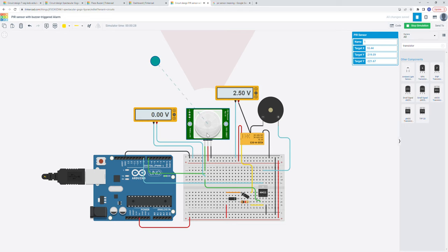So once there was an identification of the intruder, the signal here went to 5 volts, which is a logic high, and the voltage at the output of the piezo buzzer, the negative terminal, went to 0 volts, went to low, since the relay short-circuited to the analog ground.